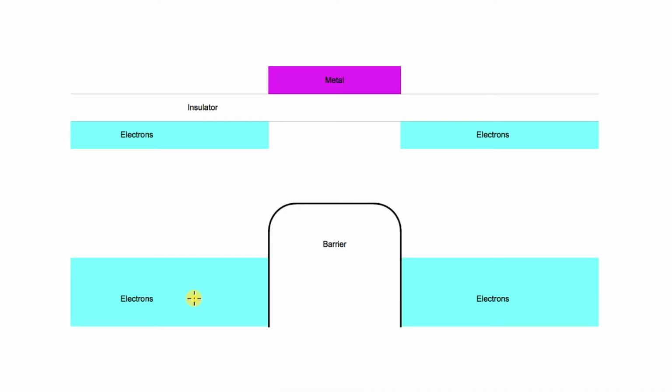So what we've done now is create a region here, which you can think of as one of those tanks. It's a tank that holds electrons. And here's another one over here, and it holds electrons. And if I put more electrons on this one, I can make it a logical 1, and if I put less electrons, I can make it a logical 0. Now, how do I connect the region on the left with the region on the right using the voltage on some other region? That's the magic of the transistor.